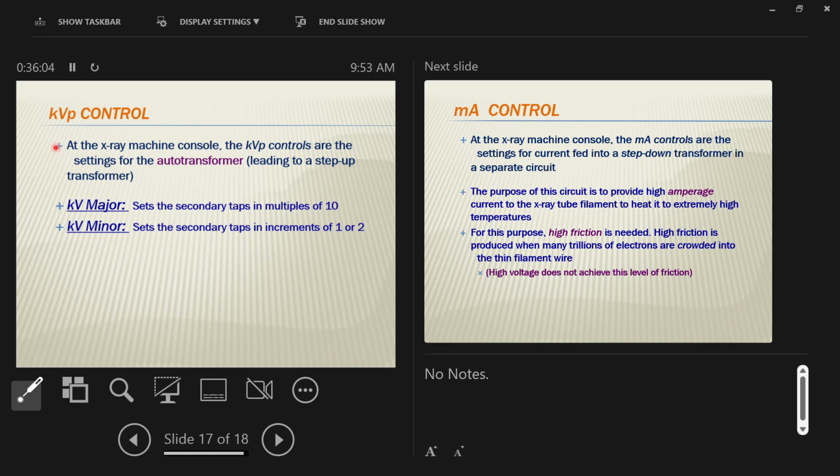But anyways, if you want to change the voltage, you need a transformer. Transformers adjust voltages in equipment. And we can build them to do whatever voltage. We just arbitrarily have to pick the specification. You change the number of windings from one side to the next, or where you tap into the number of windings. Like with the power lines, when they have the step down facility, we see the big thing with all the wires coming in.